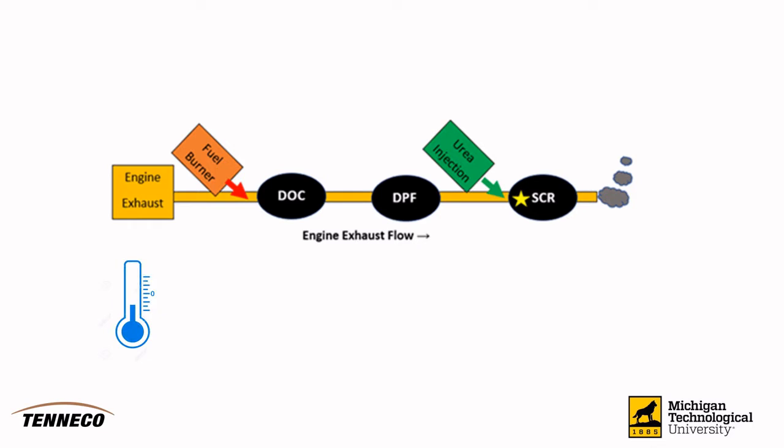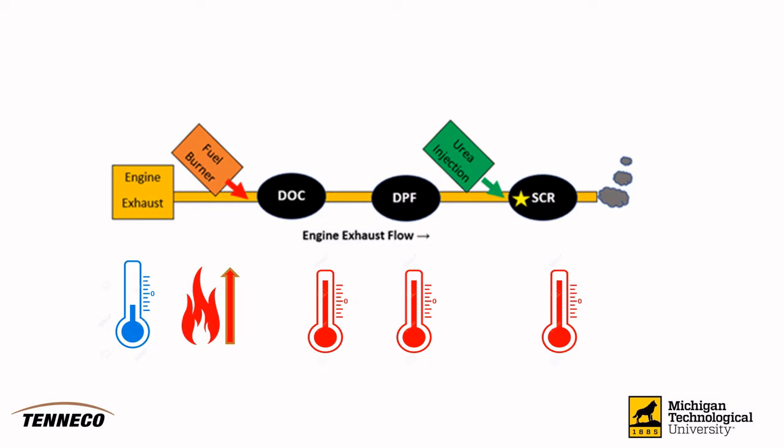In order to counteract this, Tenneco is instituting a fuel burner upstream of the system, with the goal of increasing exhaust temperatures to optimize catalyst conversion efficiencies. Our role within this fuel burner implementation was the creation of a control scheme, which would reduce NOx output by